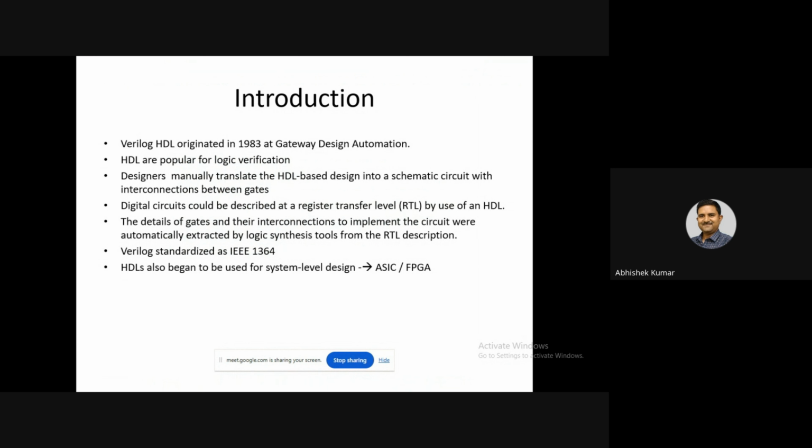Practically all the commercial ICs are ASICs, made by the very complex process which we have already seen. We have to write the code, simulate, synthesize, and generate the GDS file. This GDS file we send for fabrication, and they map it into hardware. The output of this complete process is an IC, which is an ASIC, an application specific IC.